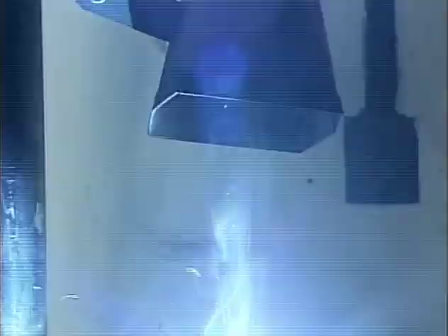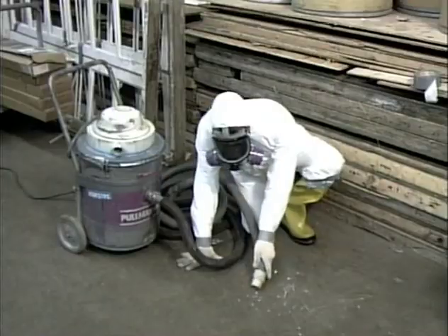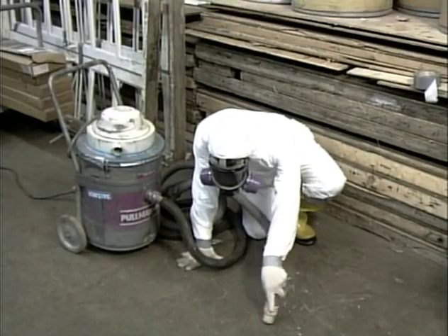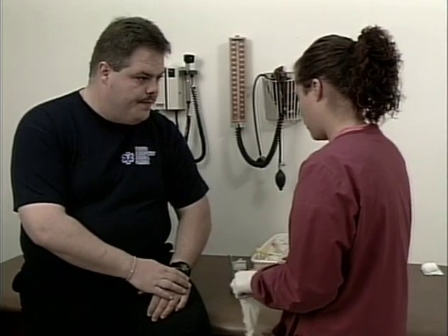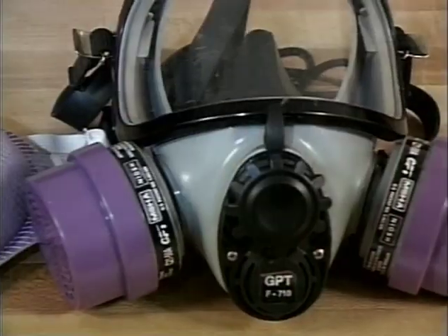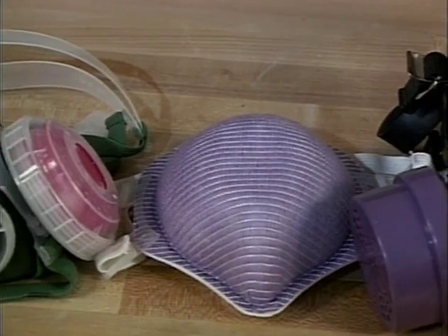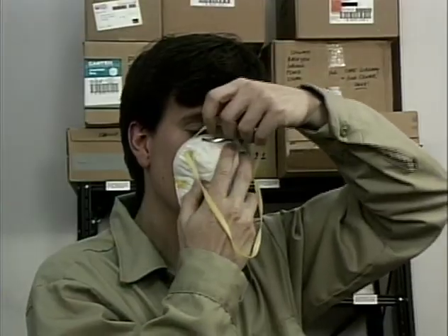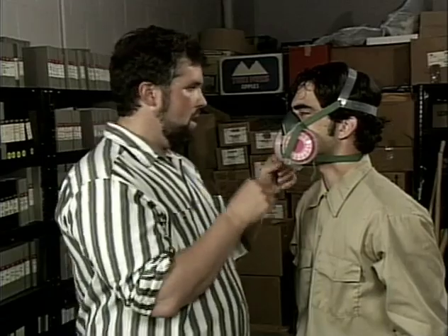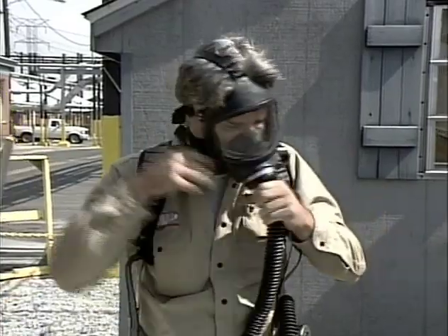But even with systems like these in place, you may still encounter situations where more protection is needed. These conditions require you to wear respirators. If you suffer from a heart condition or asthma, you should not work in areas where respirators are required unless you have medical clearance. The respirator you use must be right for the job you do. Depending on your type of work, you will use a respirator that filters the air you breathe, purifies the air through chemical means, or provides its own source of breathable air.